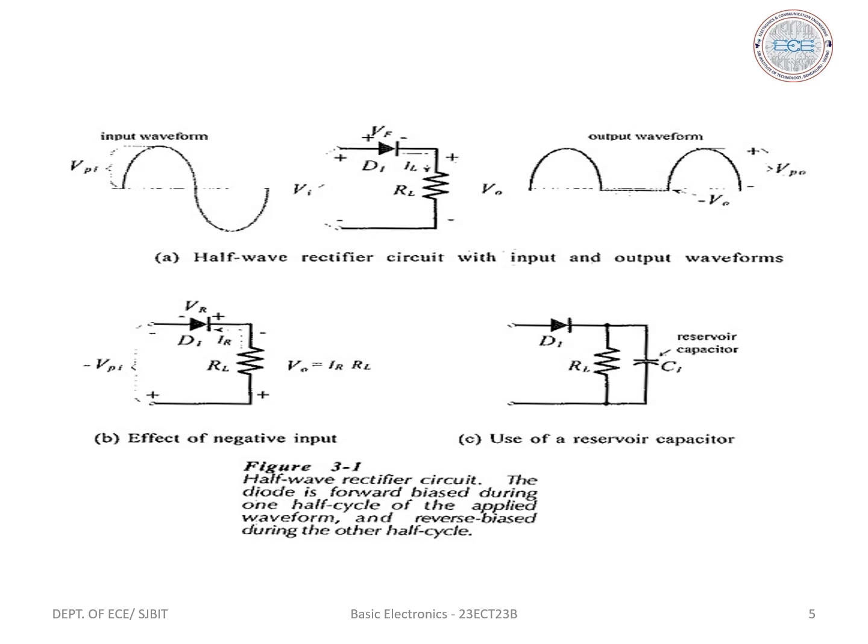Next we have the advantages of a half wave rectifier. Only one diode is required. The half wave rectifier is cheap, simple and easy to construct. The disadvantages of a half-wave rectifier are that the ripple factor is too high, efficiency of rectification is low, and transformer utilization factor is low. The AC supply delivers power only half the time and therefore the output is low.